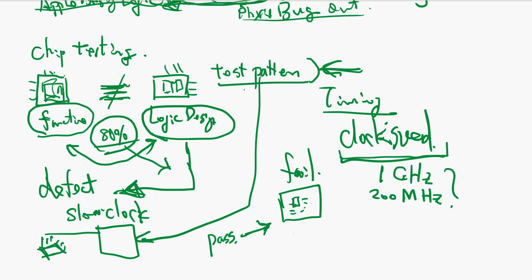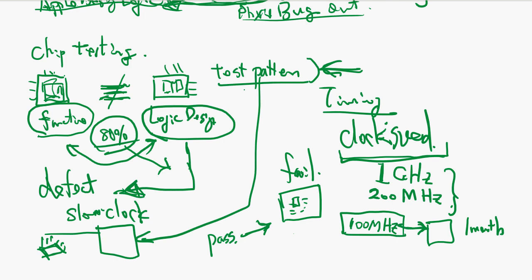This is the case when some companies use an FPGA to make a microcontroller, the CPU, and they don't know what actual final clock speed they can run. And they think, oh, this FPGA at 100 megahertz passed the test. You put it in a board and run for 1 month, it fails. Because there's some case that the test pattern didn't cover, and it fails.